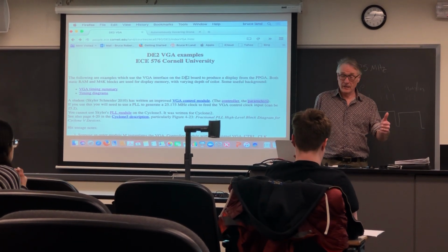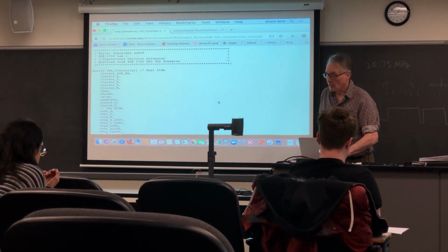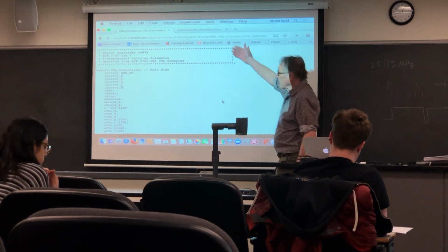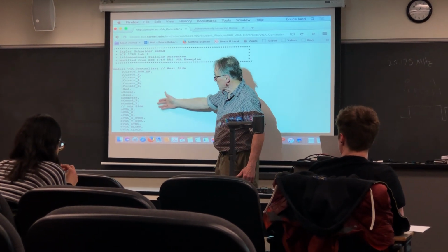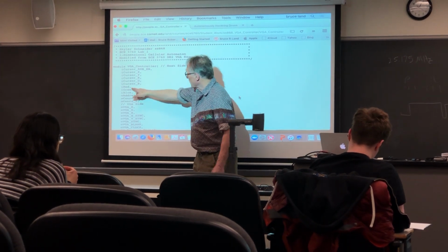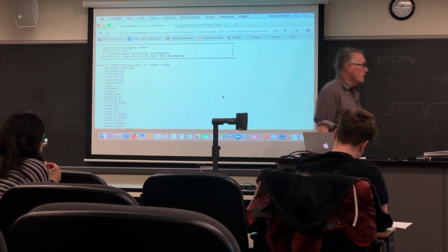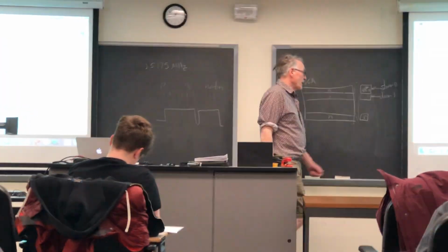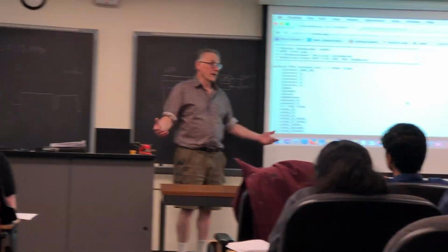The easiest way to test it is to bring up this VGA controller. Don't even hook memory to it. Hard code a red, green, and blue value into its input. Hard code red 0, green 255, blue 0, and you should get a green screen.